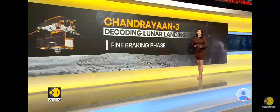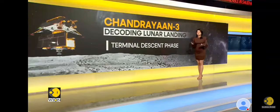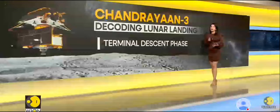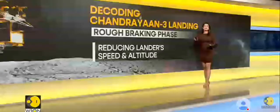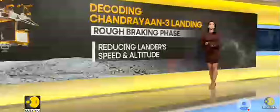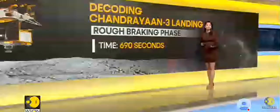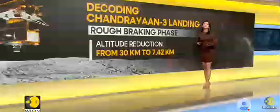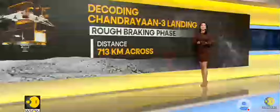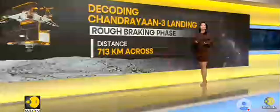Things went wrong with Chandrayaan-2 precisely in this phase in 2019. And then finally we have the most critical part of the landing, the process of reducing velocity to facilitate a soft landing at the pre-designated landing site. The complex task begins when the lander is at a height of about 30 kilometers from the lunar surface. In the crucial 690 seconds that follow, the height of the lander will be reduced to 7.42 kilometers from the moon's surface. In the meantime, the lander will cover a horizontal distance of over 713 kilometers towards the landing